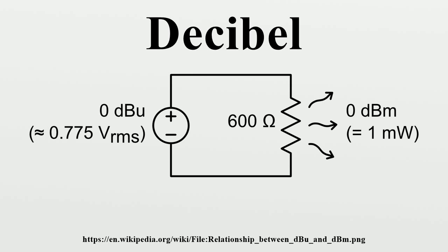Acoustics. The decibel is commonly used in acoustics as a unit of sound pressure level. The reference pressure in air is set at the typical threshold of perception of an average human, and there are common comparisons used to illustrate different levels of sound pressure. Sound pressure is a field quantity, therefore the field version of the unit definition is used, where pref is the standard reference sound pressure of 20 micropascals in air or 1 micropascal in water.